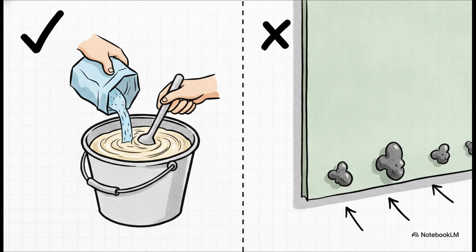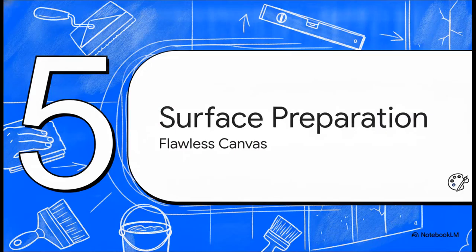Choosing and preparing the right adhesive is a huge deal, mainly because it has to be perfectly compatible with the weight of your wall covering. Take standard methyl cellulose, for instance. It usually comes as a powder, right? Well, you have to mix it perfectly, exactly to the manufacturer's specifications. The absolute crucial takeaway here is that it must be entirely smooth and free of lumps. If you leave lumps in your paste, I guarantee those lumps are going to dry hard under your wall covering and create these highly visible, amateur-looking bumps all over your finished wall. It's a nightmare.